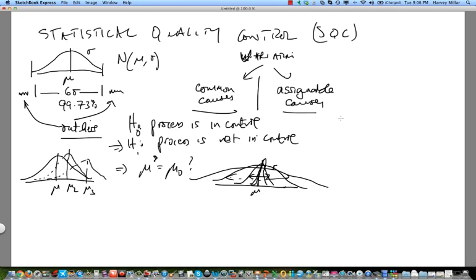So what do we use for those? So statistics allow us to basically calculate ranges. Really, that is an application of confidence intervals. So if we think about means, for example, if we take a number of samples and each of them have a sample mean, then we would expect the mean of all of the means, right? If we were to take that and add plus or minus 3 standard deviations, then we'd expect 99.73% to fall in that range. So anytime we get a sample mean that is outside of that, we have an issue.